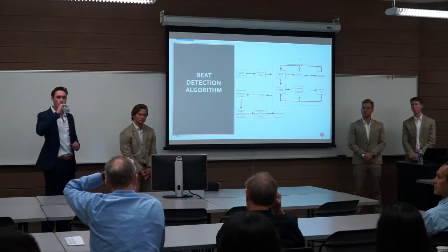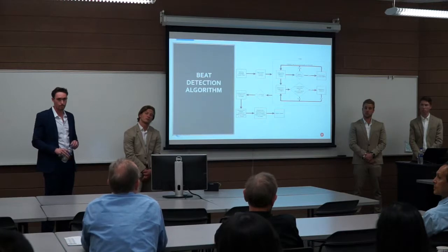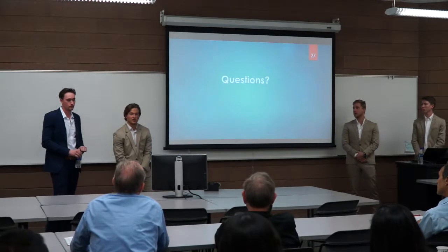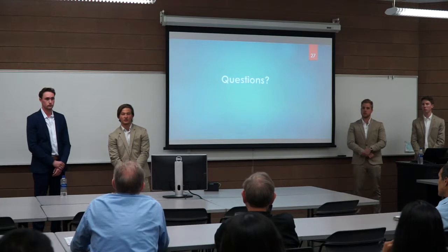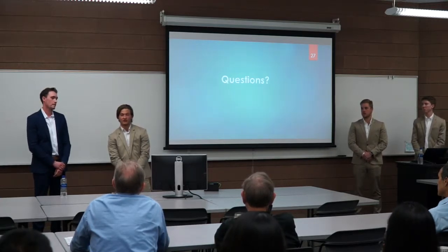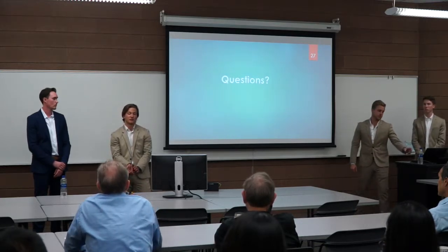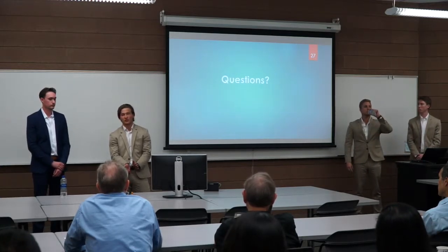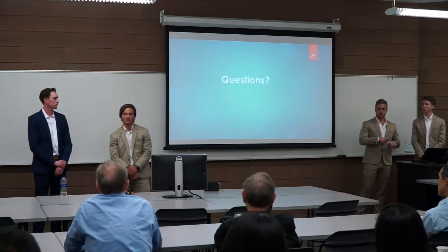So did you make an early decision that you were just going to use wave recording? Yeah, that was actually the suggested route by the Adafruit documentation itself with that I2S MEMS microphone. We initially got that to work, so we started going with that. Like I said, if I were to redo this, I probably would not use arecord, a Linux function that was added to the module, and I would create my own I2S communication protocol.